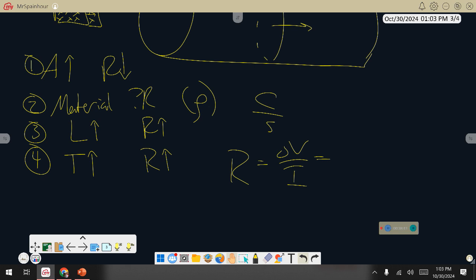This just allows us to measure a specific property. So let's put resistivity up here. Boom, resistivity. And that makes sense: that number is very low for metal, therefore resistance would be low, and very high for air. All right, now let's put all the rest of these up here in basic mathematical modeling fashion. More area means less resistance. So where do we put it? On the bottom. More length means more resistance, therefore on the top. This is where they usually stop in the equation.